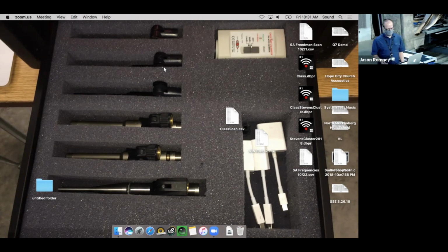The difference there is that Smaart is source-independent because all it does is compare the difference between two sounds. And it doesn't care what those two sounds are. That could be two microphones. That could be a microphone and a direct audio input from some device. It could be a microphone and a noise generator that's internal to the computer. It could be two different line inputs from two different pieces of equipment. Like it just doesn't care, right? It will just always tell you the difference between two different sounds.